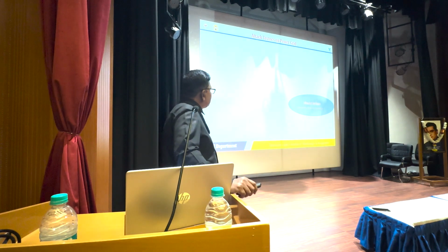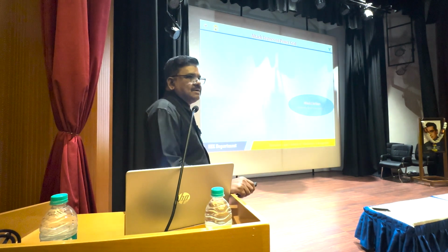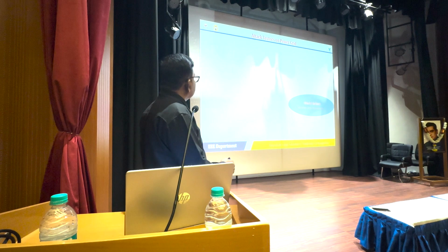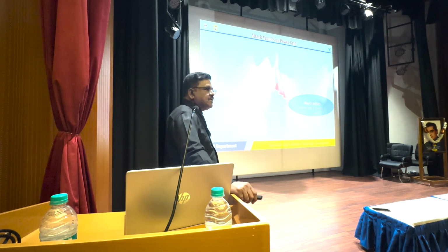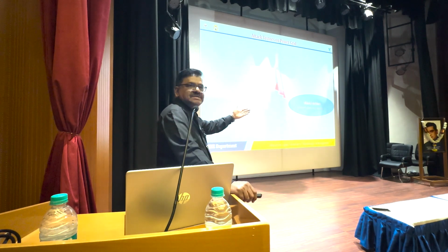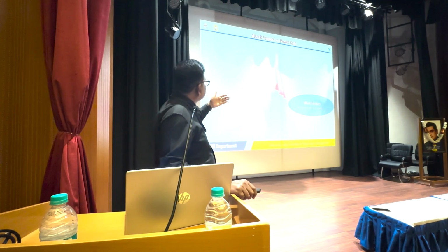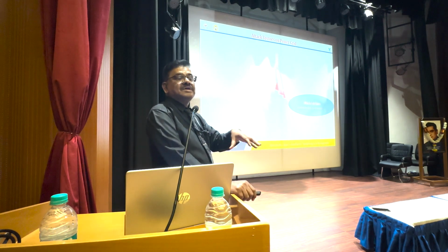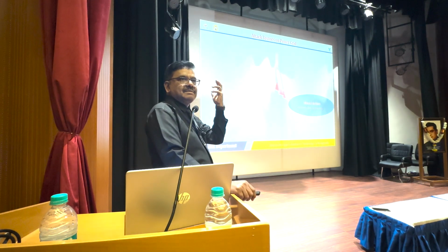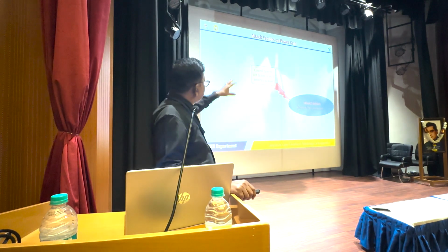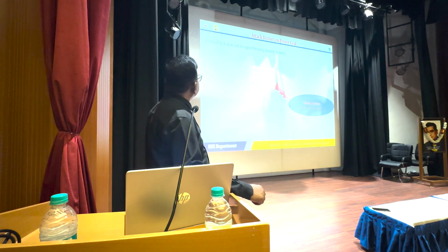Attack surface. This will increase the risk to operations or the control system operator. First let us see the attack surface. Control systems are not designed keeping security in mind. Because of this, an attack surface is possible. Why are control systems not designed keeping security in mind? Because the control systems in the conventional power system were designed almost 30-40 years back. When they were designed, they didn't have this concept of cyber attack. That's why, however, they are updating it now. So this is one reason the attack surface exists.